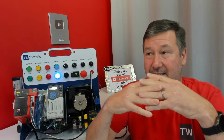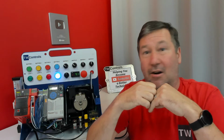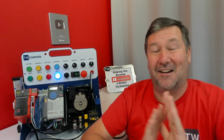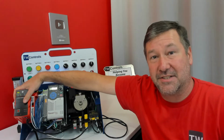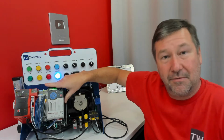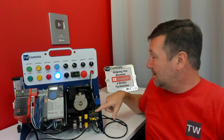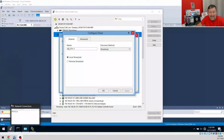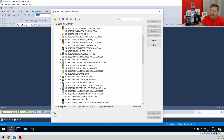With the broadcast discovery method, your computer actually sends out a packet and says, hey, are there any Ethernet/IP devices out here? And all the Ethernet/IP devices, notice that was not all the Ethernet devices, all the Ethernet/IP devices say, hey, here I am. So this CompactLogix is going to send something back saying that. This PowerFlex is going to send something back. This Turck I/O module, it is Ethernet/IP, it'll send something back. So all those types of devices will respond, and that is what is going to be filling this list that you see through here.